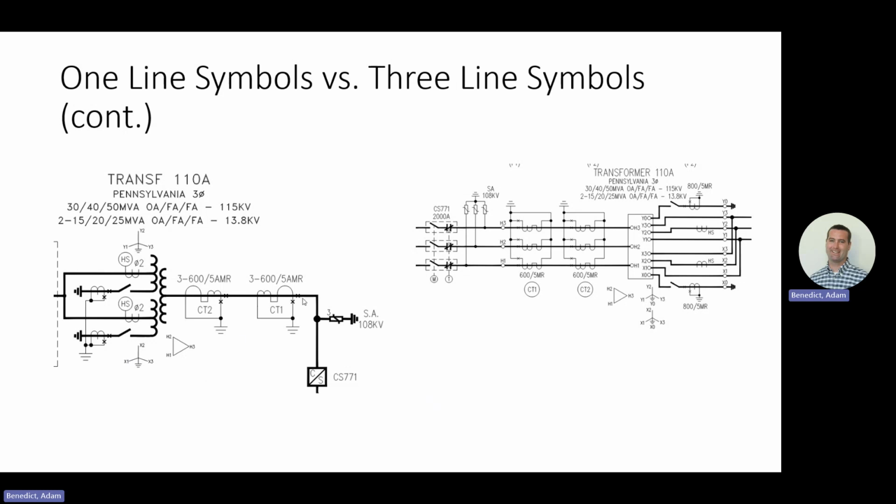And ideally, when you're setting up your AC schematic, and they're not doing it here for one reason or another, you want your one line and your three lines to be oriented the same. So where you have a circuit switcher on the right, here you have a circuit switcher on the left. So, a good design practice. I'm sure they had their reasons for it, and there's reasons to deviate all the time. But ideally, that's how you'd want this, circuit switcher on the left, or vice versa, you'd want this on the right, based on the one line.